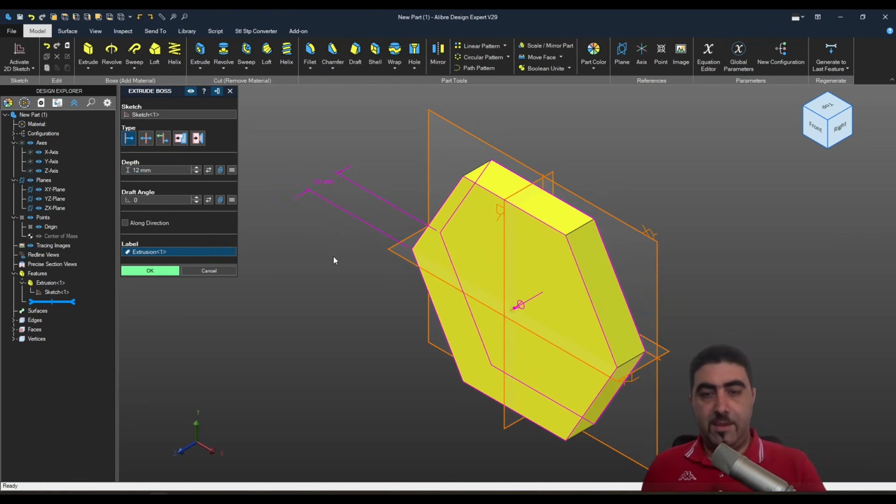Now, the main differences in V29 is here. And here also lies the reason the tie tab is dead. So let me just remind you, in V28 and before that, we could do the tie tab move in both Extrude Boss and Extrude Cut. And what was that? You did a Shift tab and the drop menu that selects the extrusion type would be highlighted. It's no longer a drop-down menu. That's the main reason this doesn't work.